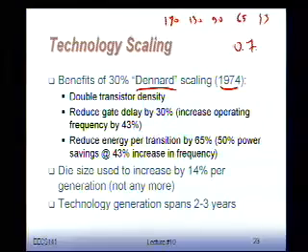Now, why 0.7? Why is that an interesting number? Well, the more interesting number is when you square it. When you square 0.7, what do you get? 0.49. So what basically happens is that every chip gets 50% smaller. It's squared, right? You have one dimension here, you scale it by 0.7 in size, and 0.7 on the other side means that for the same functionality, the area of a chip scales by a factor of 2 from generation to generation. That's what that 0.7 factor does.